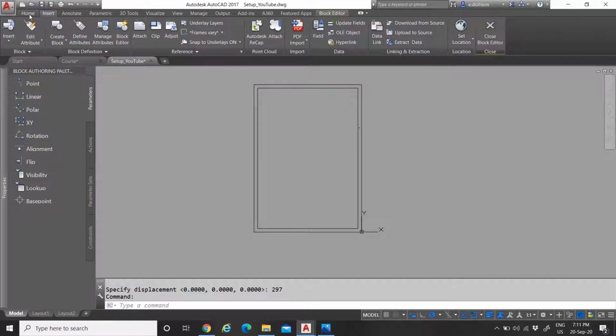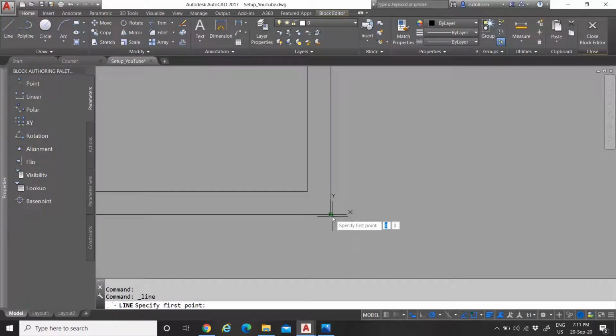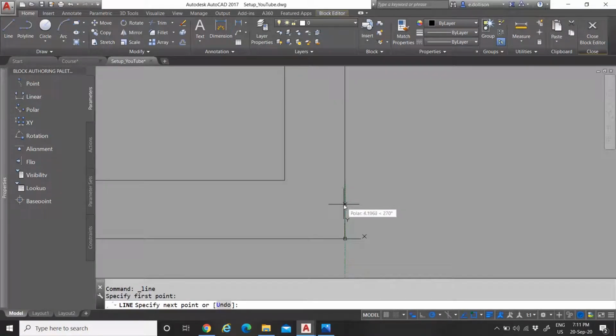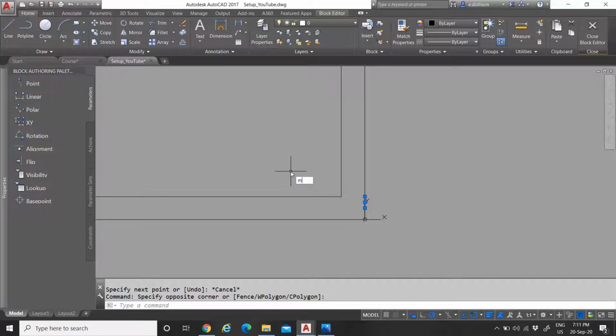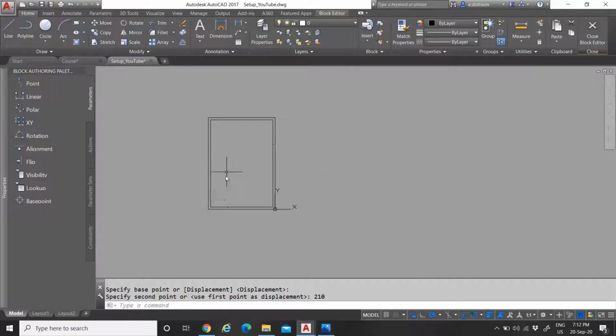So now we will do the same for the other side. Drag it all the way now on the side. Then you click, make it 5 millimeters, enter, press escape, select the line, type in M for move, and then you click any corner, it doesn't matter where, just click and then you drag it, and here you can punch in the side or this placement you want it to be. That would be 210 because my paper A4 is 210.